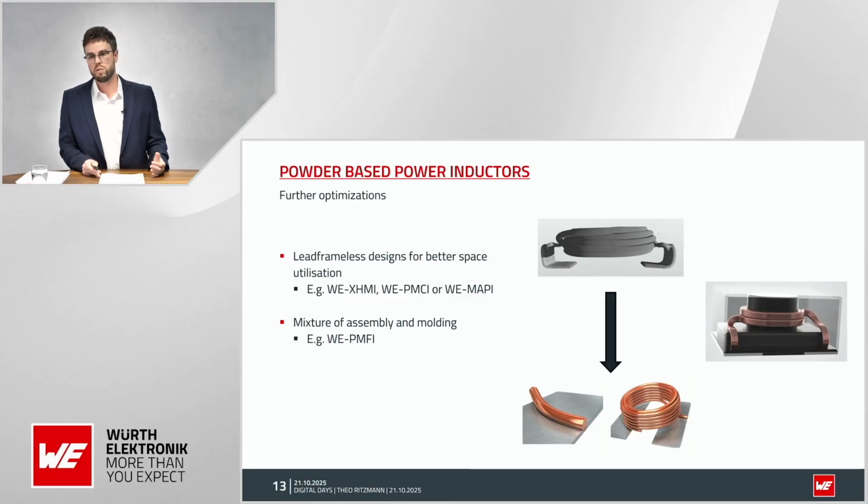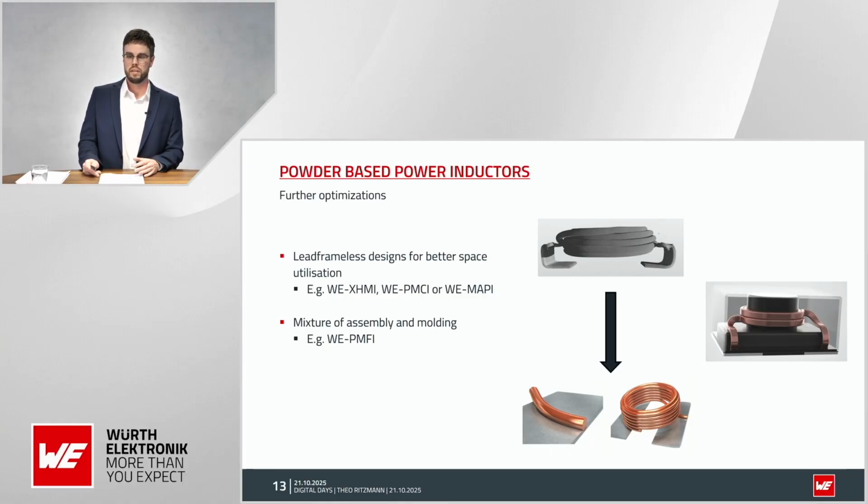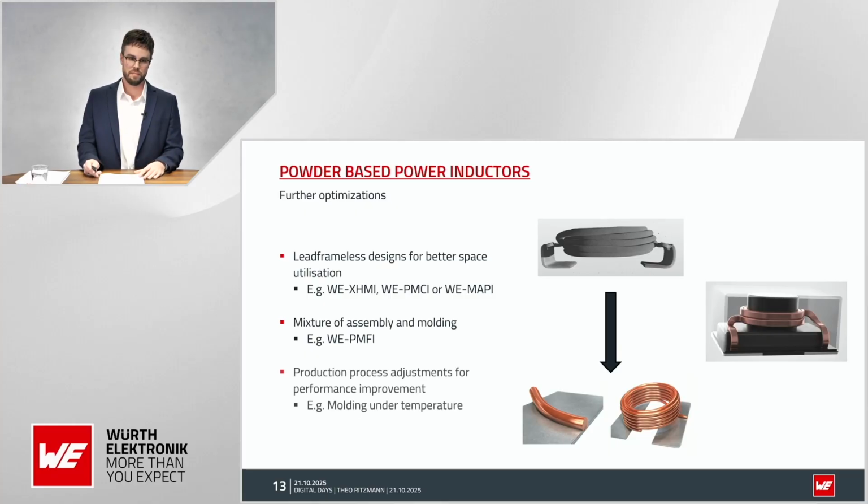Then also one trend was that a combination of assembly and molding became more popular. So that first of all, the coil was assembled on an inner core and then went later for the molding process. And then there happened also some production process adjustments to improve the performance even further, for example, molding under temperature.